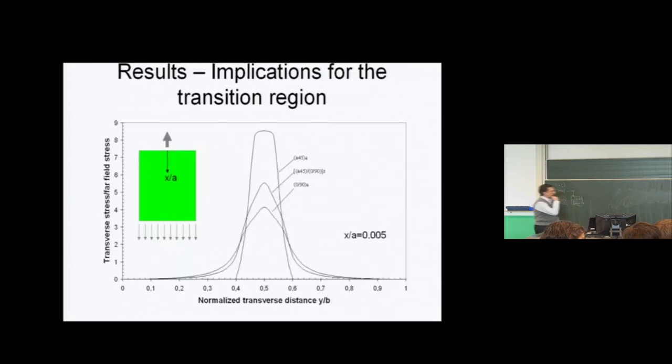If I now look at my transverse stress, that's the sigma y stress, as a function of my y distance, again, I see significant differences. Now, the plus or minus 45, it has the highest peak, but it's confined in the narrowest region around the center, while the other two have lower peaks and they again go further out, so they would need larger reinforcement in the y direction.